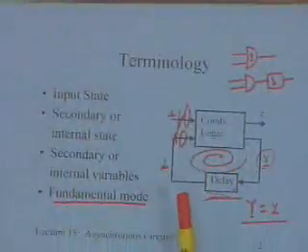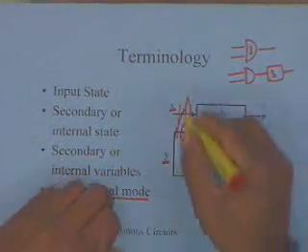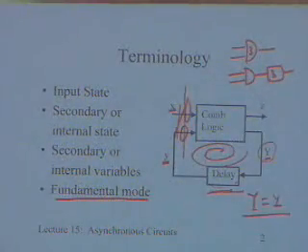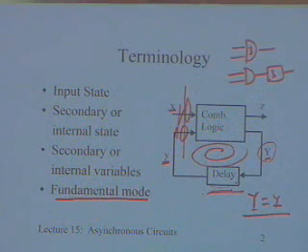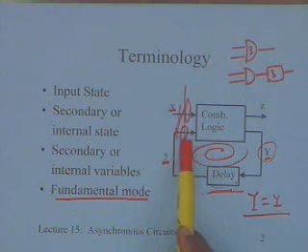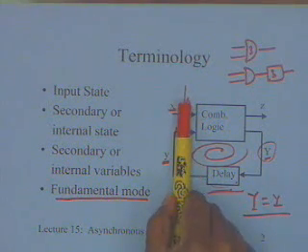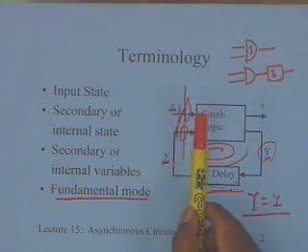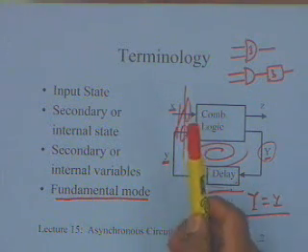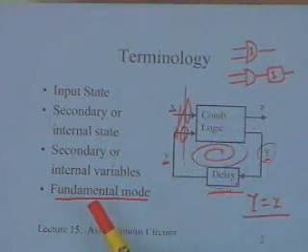If I take a snapshot of this, what is happening at this particular point? My input was 0 0 and suddenly my input is 0 1. If I now look at this, I am not in a stable state because this particular input change has not really resulted in all the changes that are going to happen.